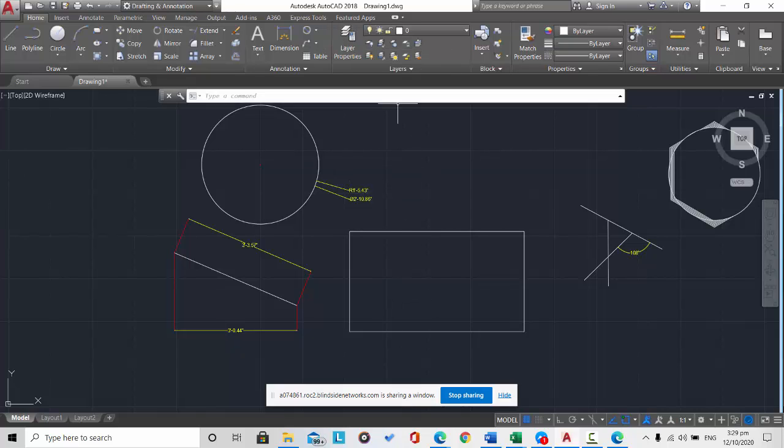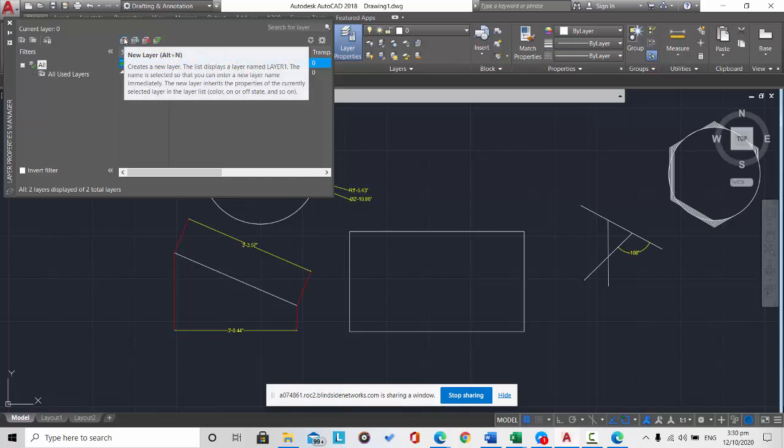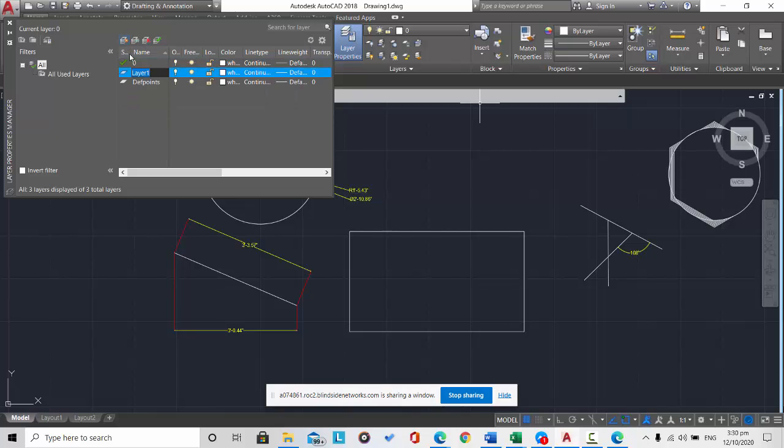No? How do we do the layer properties? So, when we set layer properties, maganda rin matutunan nyo tong layer properties. We can do that by clicking it and then lalabas sa inyo tong dialog box. Ito. Then from here, we have a default layer, no? But we can add another layer, no? So halimbawa, ito, pwede natin i-click Alt plus N, or we can click this one as our new layer. So we can call this, for example, dimension layer. Yan. That is our dimension layer.